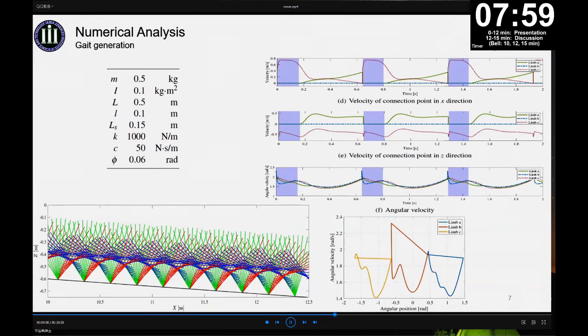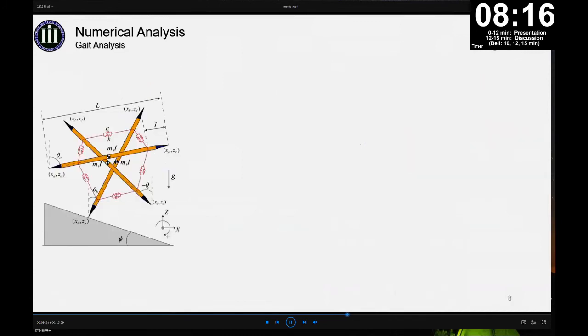Let the robot work on the slope at any initial speed. We record it from step 40 to 50 because the step period has converged, and then we get the phase plane plot like this, and it can be seen that the limit cycle gait is achieved.